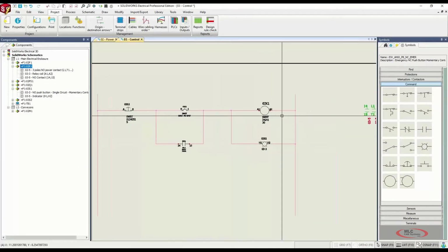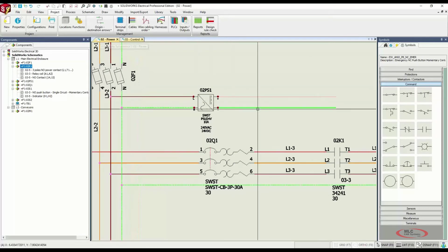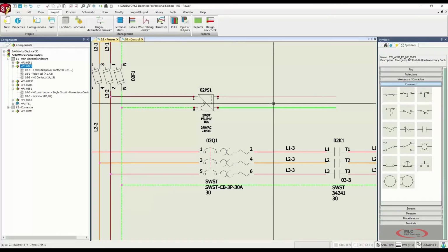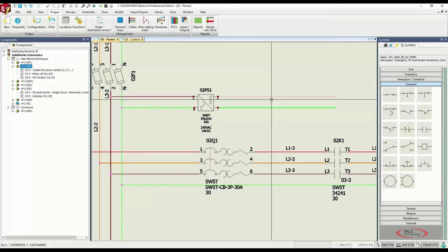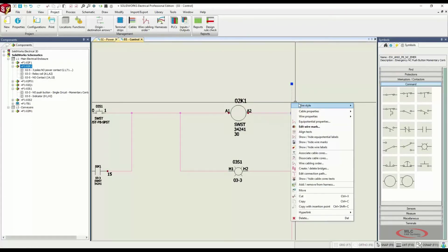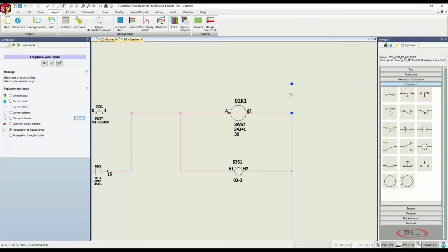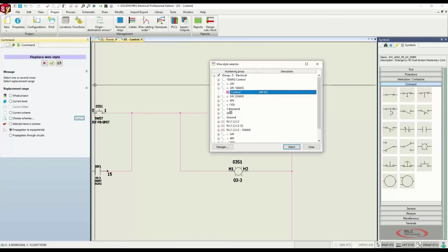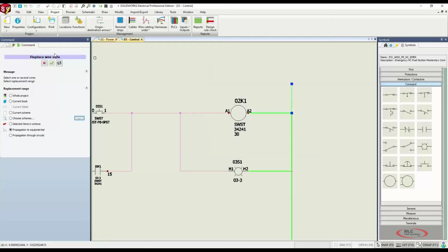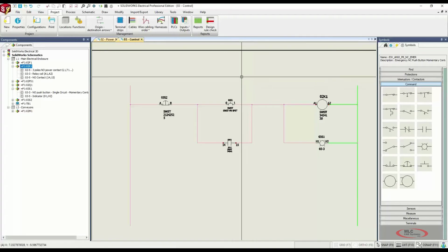So at this point I need to change the wire styles over here on the right side. Now if you notice back here on our O2 power page, we have two different wire styles coming out of our power supply, and that's perfect because we need one to be 24 volt DC and one to be ground. Now, if I come over here and right click on this and go wire style and choose to replace it, I can replace this to Equipotential, which means everything that this is touching on these sides of these symbols. I can hit my green check, and now it's going to ask me, okay, what do you want to replace this with? Well, I'm going to replace it with this ground here and hit select. So now you'll see that we have both of our wire styles lined up, and that's perfect. We're ready to rock and roll.